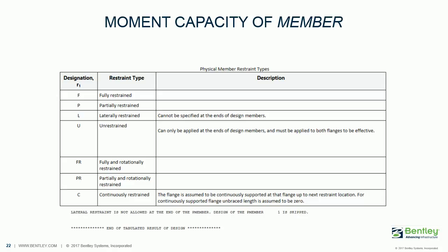So you need to take note here that this lateral restraint L is only for preventing the lateral displacement, but it won't restrict any sort of twisting of the section. Now, U is something we call a nil restraint. It's a cross section that does not comply with any sort of F, P, or L, or we can call it the unrestrained, meaning there is no restraint at all.